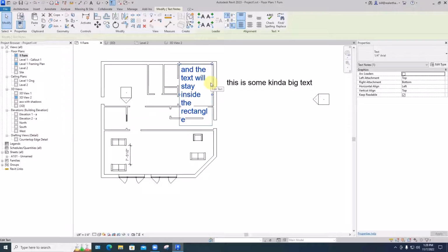But by and large, you should be thinking ahead to say, I guess I really would like this to plot an eighth of an inch equals a foot and set it that way. And then as you keep working with it, your text will be appropriate. You don't want to have to change scales radically and have your text shift all over the place. Experiment. It's really nice. It works great.